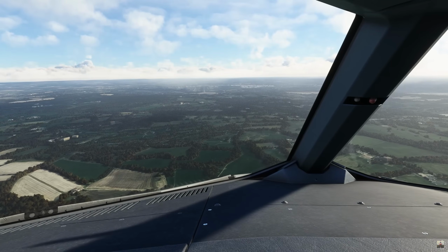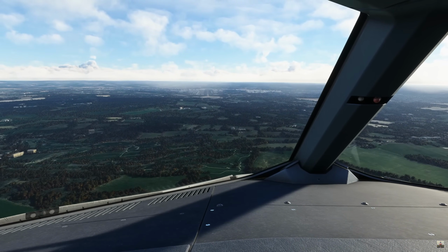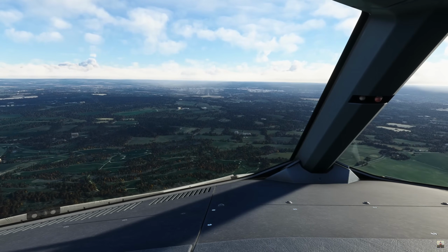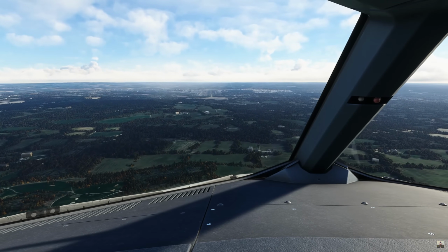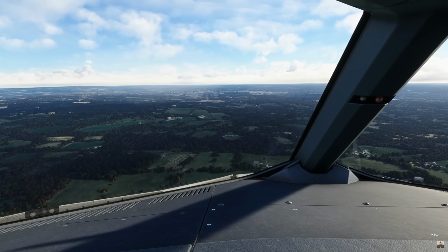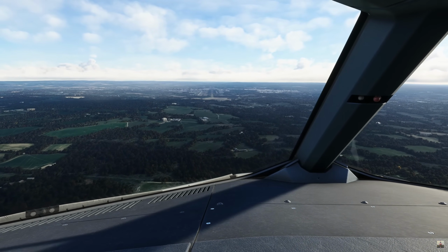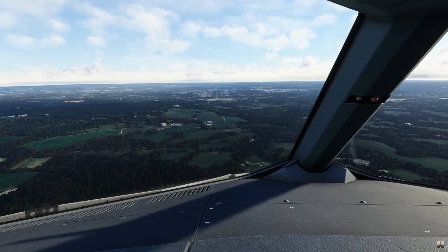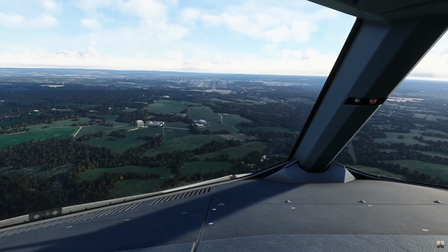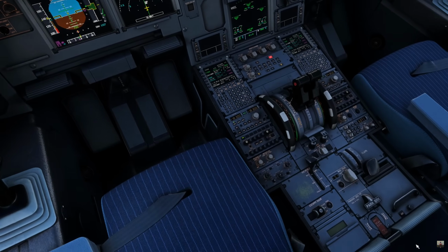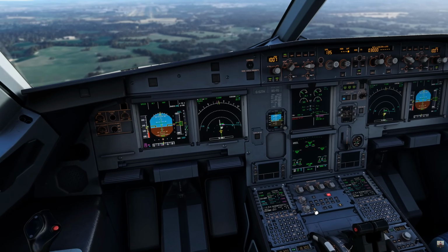So everybody, just like that, we've completed the setup for a full flight from London Gatwick to Edinburgh, using the MCDU to manage every phase from initial setup, departure, all the way through to approach and landing. And I hope that what once seemed like an overwhelming system is now something you can confidently navigate. The MCDU A320 isn't just a flight computer. Like I said, it's the heart of modern aviation automation, and it just allows pilots to fly more efficiently, safely, and with greater precision.